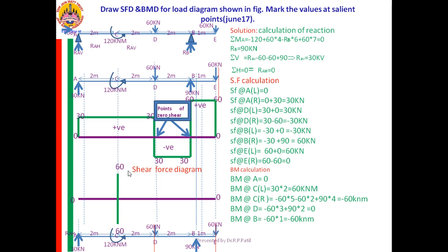How is it to be joined? You go by the SF. SF indicates a constant there. Next to constant is the linear variation. It means you need to join it by means of an inclined straight line, or simply a straight line. Like this. You take the values at the other coordinates, then you join them.